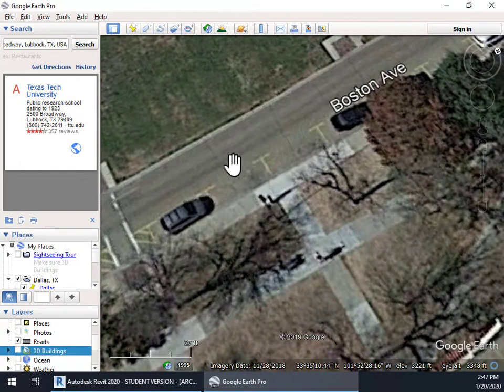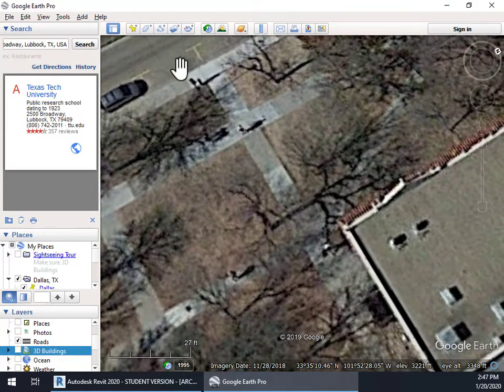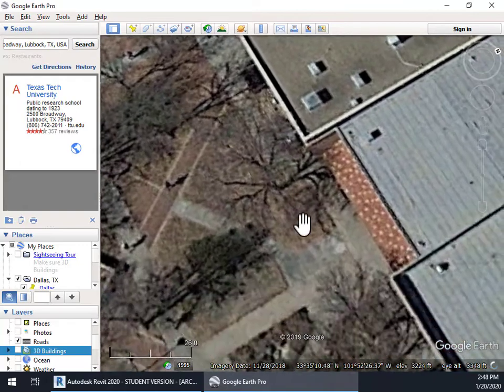The street comes in at 3221, which is a 4-foot drop from where we are. I know that from the curb height, a conventional curb height is only 6 inches tall. So you'll see this reaches 3222 once again. So it's going from about 3221 right here to 3225. So that's a 4-foot drop more or less across this.